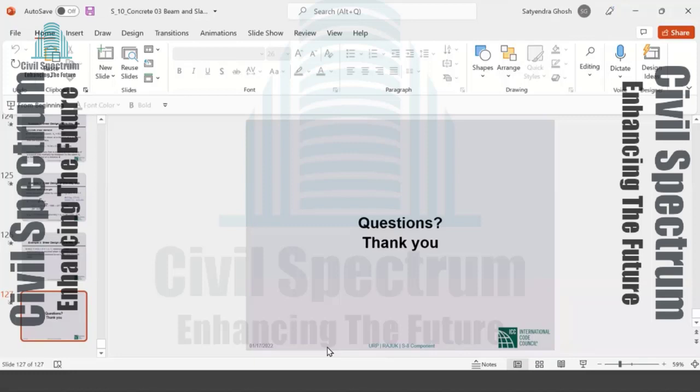So that's where I would leave it. It is not common to use that in members that are prone to web shear cracking. Not common at all. But if you're looking for something to try, it will not be wrap. It will be the fibers in the concrete mixture.